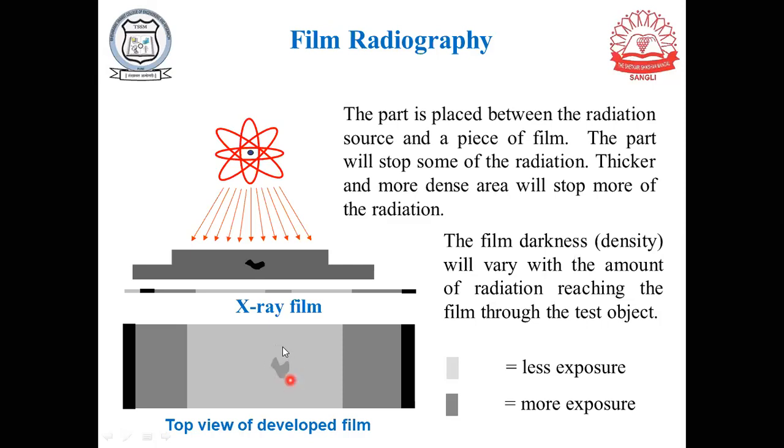One more thing you can observe during X-ray testing: if the component is thick, its image is light in color. If the component is thin, its image is dark. The darkness of the film depends on the amount of radiation reaching the film through the object. Light color means less exposure to the rays, and dark color shows more exposure to the rays. So this will give you a clear idea.